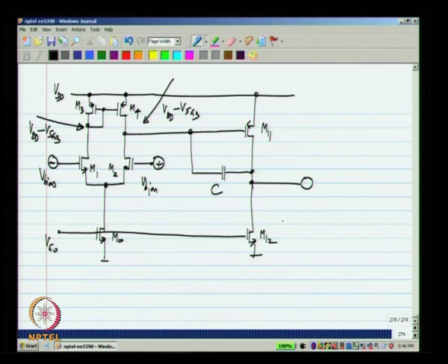At a voltage Vg0, M12 tends to carry a current I12 if it is in saturation region. Okay. The square law stuff holds only in saturation region, and this current I12 will be carried if it is in saturation region. Now, if you look at this, we have M11 which behaves like a current source and M12 which behaves like a current source connected together. Okay. Obviously, the current in M11 has to be equal to the current in M12. Now, can both of these be in saturation? It is possible if the voltage happens to be biased in the middle.